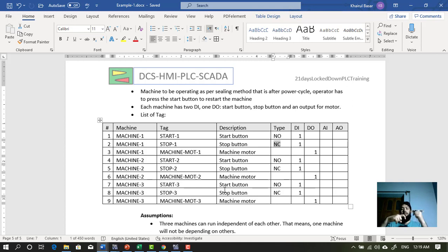So when someone presses this side, it goes down this way and breaks the circuit. It's normally connected, but when someone presses it, it becomes disconnected. So the circuit breaks, and the signal which was previously going to the DI input is now not going anymore. So the PLC gets a negative signal, like 0.